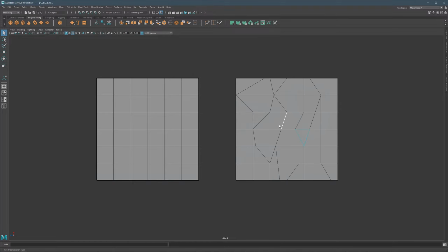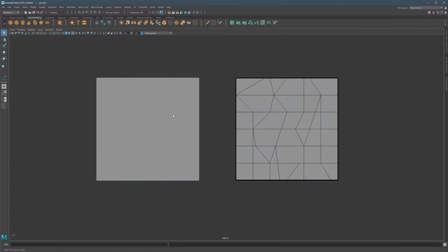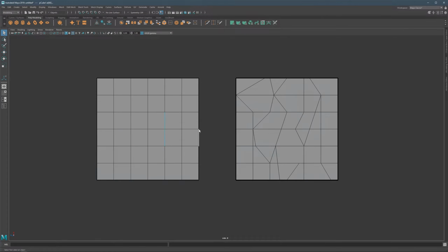Here, what we have is a lot of uneven spaces. A small triangle here and then a quad here, and it's very, very uneven. So this is again something else that we're going to search for. The more evened out the topology or geometry is, the better it will calculate and the better it will deform. What I mean is that we don't always have to search for evenness. It's just important that we spread it out evenly.